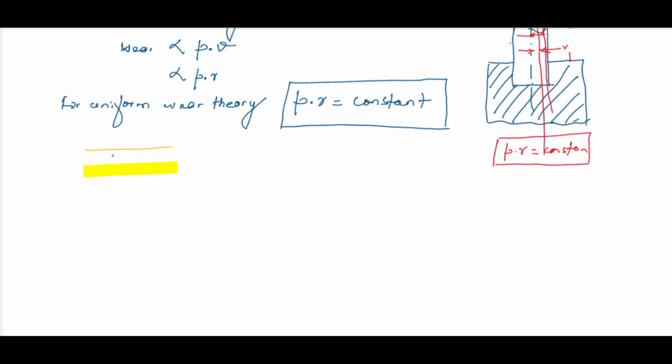So in order to have the same stroke width, as the chalk gets older, I will apply less intensity of pressure while writing, so that I can have the same thickness. So the same principle is applied here in the uniform wear theory. We will decrease the intensity of pressure as the wear increases, in order to keep your PR a constant. Okay, so this is the fact.